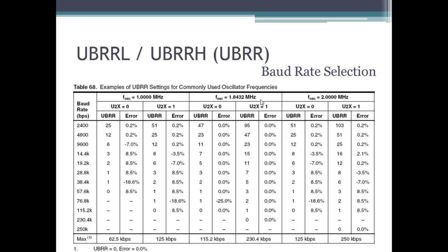So if you've ever opened up some piece of consumer electronics and you see a can crystal in there, and the crystal reads some arbitrary particular frequency like 1.8432 megahertz, you now know that it's been chosen so that divisions of that work out to be an exact multiple, so they target the frequency quite well. Okay.